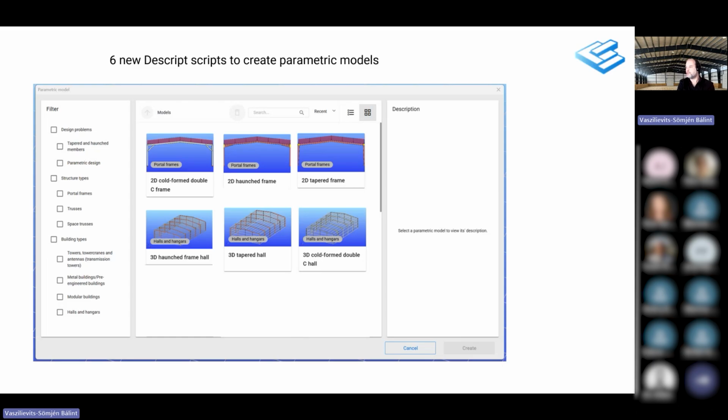What is different is the structural solution, the primary structural solution used for the load-bearing structure. One is following the most traditional approach, where hot rolled beams and columns are used, and near the column connection, haunches are used for the region with the higher bending moment demand. The other option uses welded sections, and the third, probably the most interesting, uses cold formed sections back to back to each other. These macros can be found in the parametric model library of Consteel, but as always,